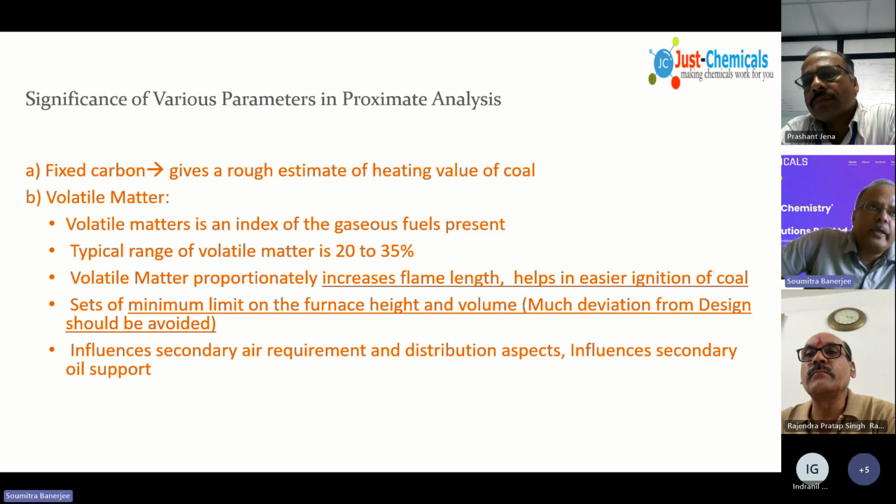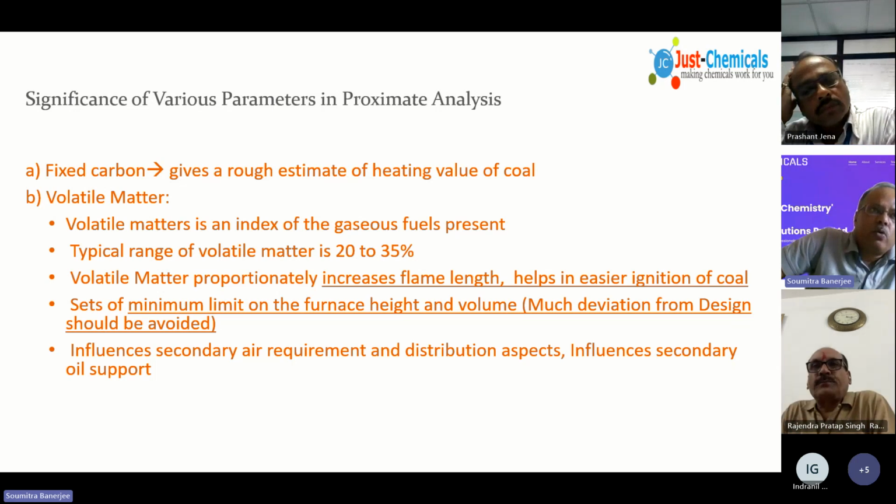Then you can try secondary air, because the unburned carbon may be due to lack of air. That is also a very important factor which I saw in Vikram Cement. Their air was circulating more in the bed itself. It wasn't going up with the volatile matter to get the volatile matter also burned. So they had this challenge of high carbon.